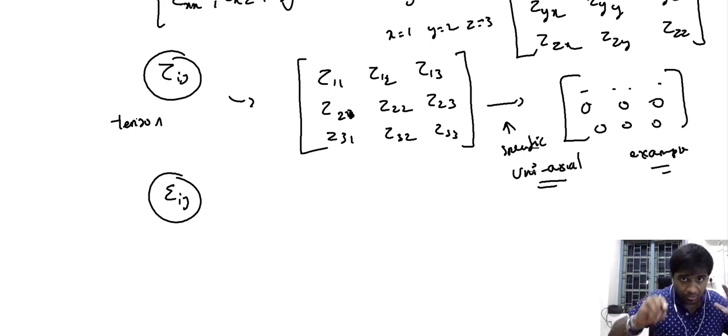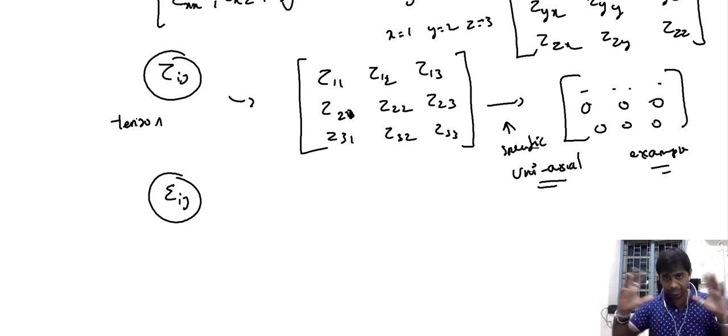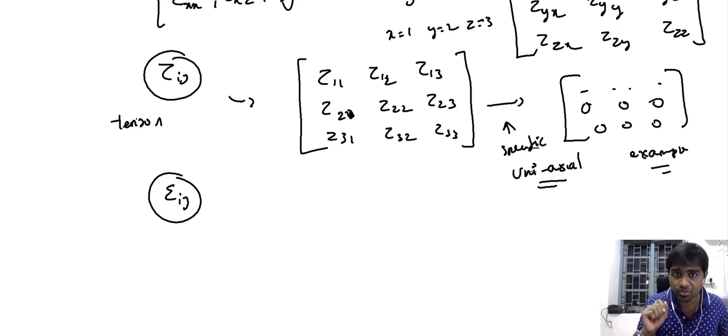So in all theoretical models where the stress is involved, be it the stress to introduce some elastic strain or the stress to introduce a plastic strain, wherever the stress is involved in a theoretical model, in materials research, the stress is expressed as a tensor, primarily because the tensorial representation of the stress is the most generalized one, and from that tensor representation, we will be able to deduce the specific case of uniaxial tensile loading for a plane that is perpendicular to the loading direction. So whenever you come across any article that includes stress in its theoretical model, it will be in the form of a tensor, and this is the reason why.